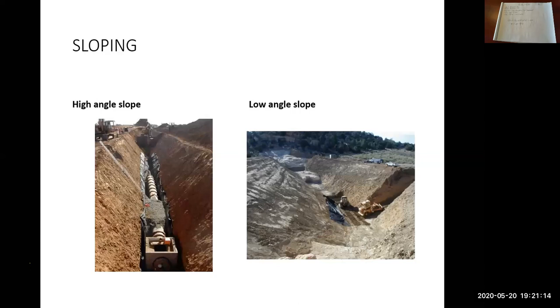So here's a utility installation. Looks like the ground is good enough that the slopes are steeper than 1-to-1. So they've got some bedding in here over top of the pipe. It looks like it's being wrapped with a geotextile. So there's your crew access, so up this ladder.